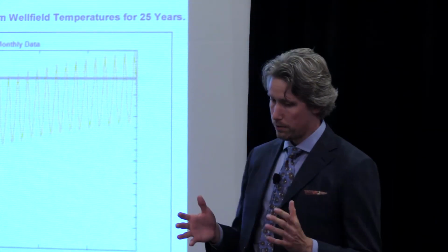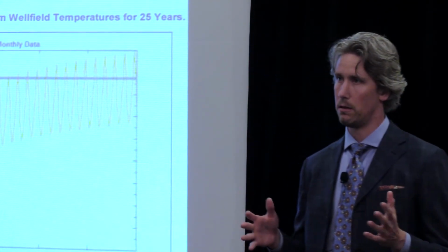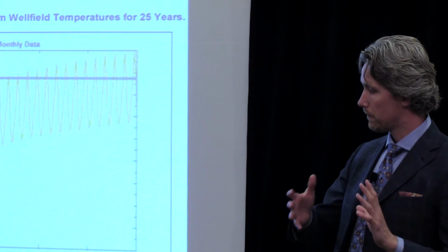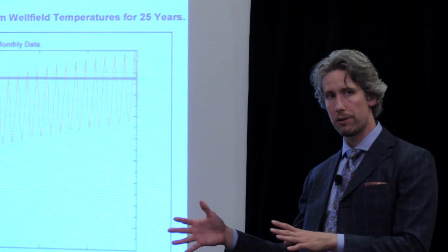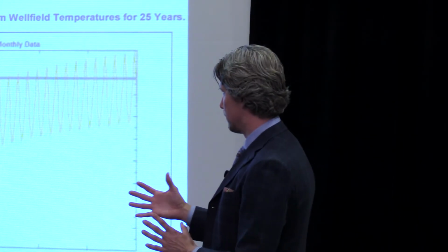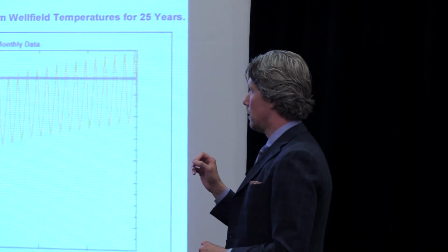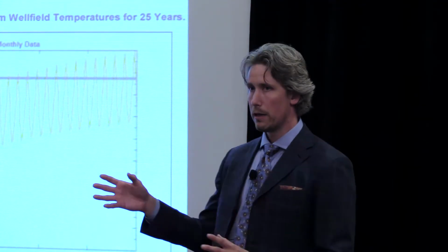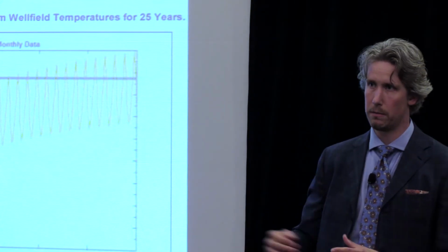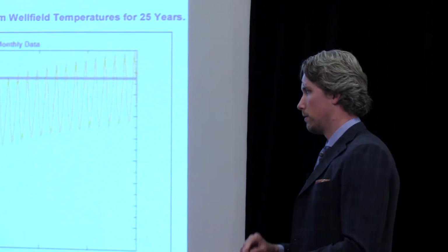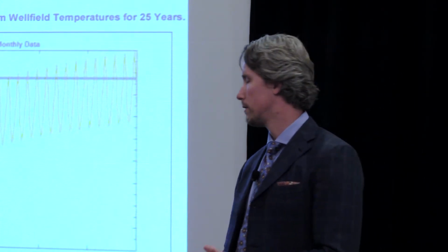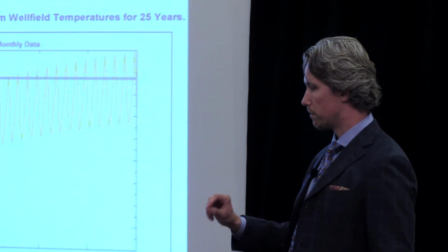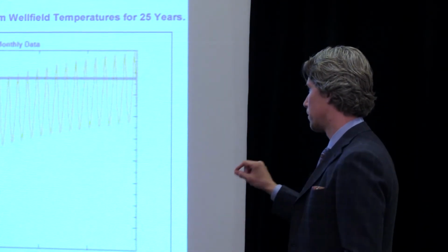And we took our energy model, which happened to be TRACE, but that's really neither here nor there. You're able to export the annual block loads from TRACE. We were able to export those, and then we used some software that was a well field simulator, and we were able to import those annual loads into the well field simulator. That well field simulator also included the layout of the wells and the thermal conductivity of the ground, all these different things. And it was able to predict the long-term temperature of the ground loop.